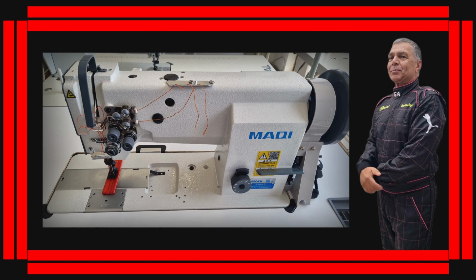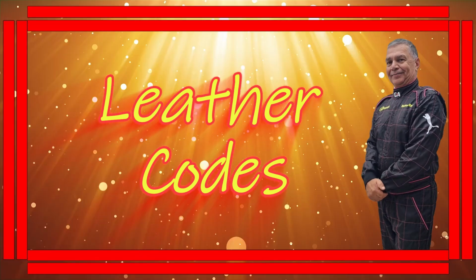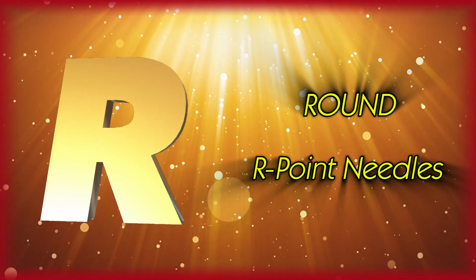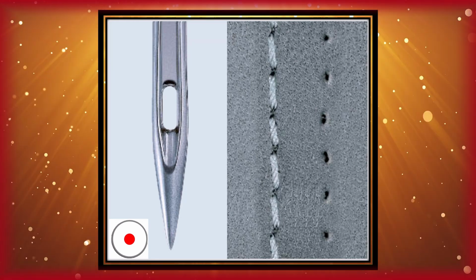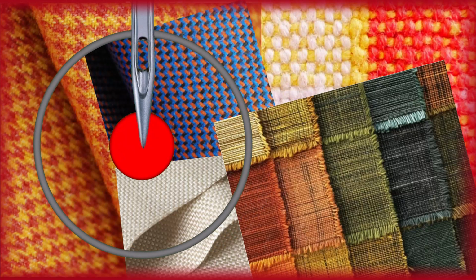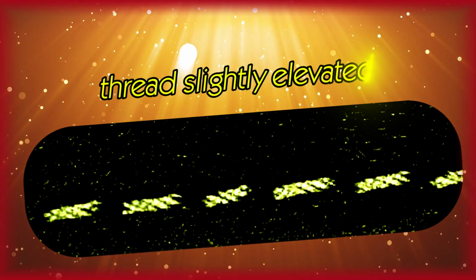And since Bost specializes in walking foot industrial sewing machines, here's the breakdown of the must-have needlepoint codes for leather. This is your everyday hero for soft leather fabrics. R-point needles, also referred to as universal or round point needles, are used for general-purpose sewing. These needles are standard for lockstitch machines and are often applied to woven fabrics and soft leather. R-point needles produce a slightly angled or irregular stitch, with the thread being slightly elevated.